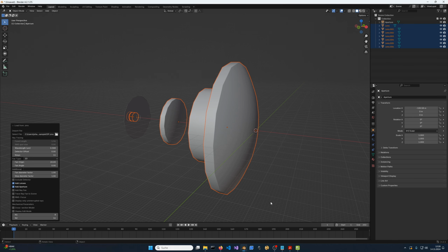Alright, so on the topic of aspheric surfaces, I would like to move on to the next designs. And now I specifically want to move into the category of mobile lenses, i.e. lenses used in smartphones or similar devices. They use multiple aspheric surfaces and in some cases even very complex aspheric surfaces where you can very clearly see the deviation from a spherical shape, even more so than for the case of the parabola that we have seen in this fisheye design.